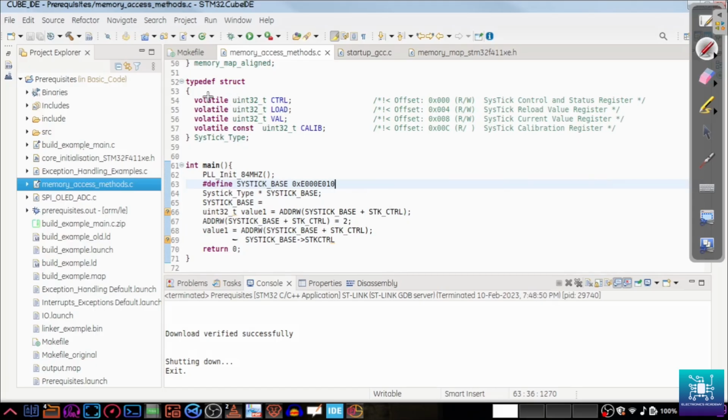The register addresses, the register locations, are already mapped by the structure. As we said, turn the structure over its head, and these values will map the register location, because the structure means to point at the offset 0, offset 4, offset 8, offset 12, and so on.